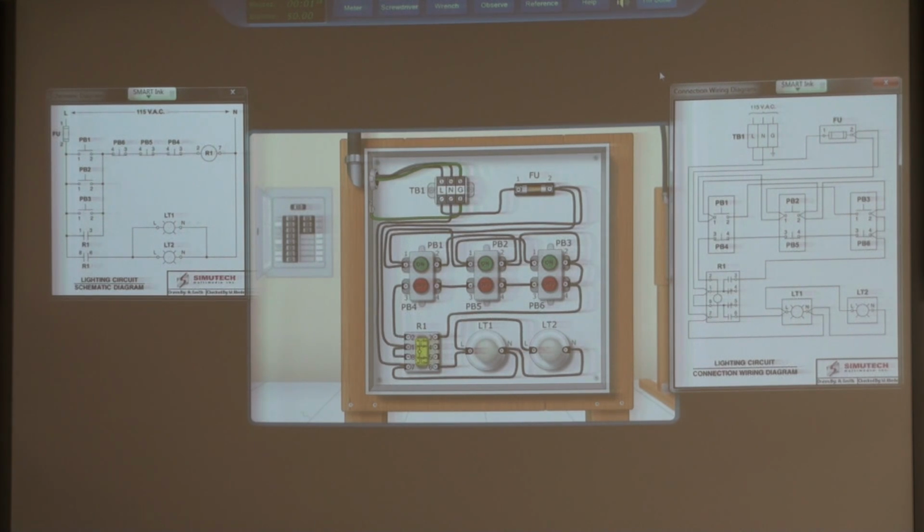What type of relay contacts on a relay are true when a relay is not engaged? The normally closed are the true state, and they'll exist that way on a mechanical relay, even when there's nothing hooked up. You can hold it in your hand, and literally those normally closed relay contacts are closed.